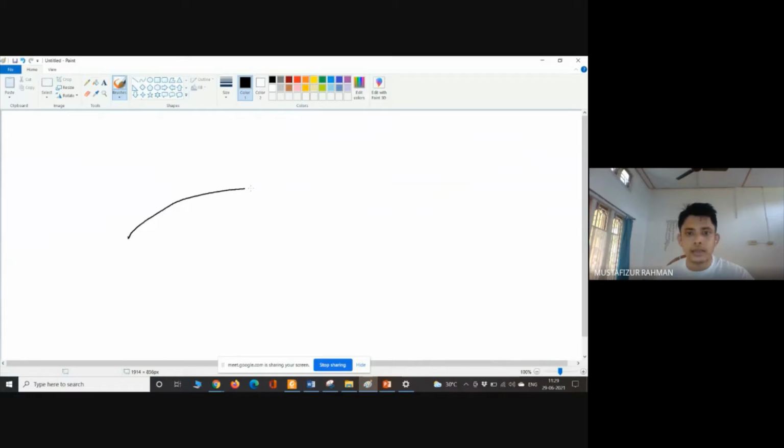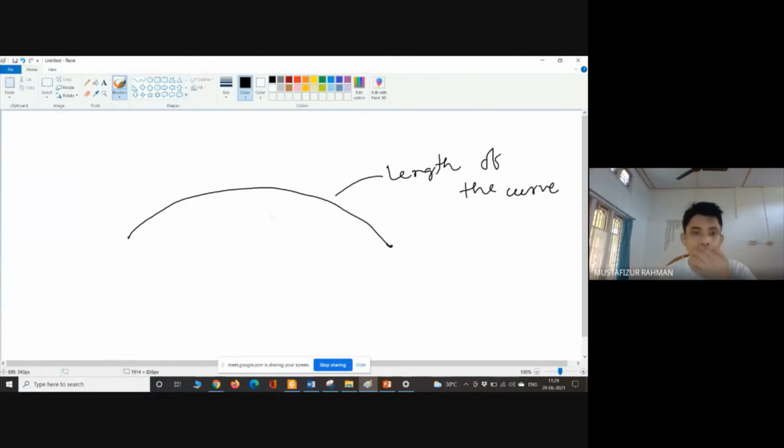So it was like this. This was the curve. We know the length of the curve, right? We have to divide it into suitable chords like this, a suitable number of chords. Most values are 20 meter. These are 20 meters, but the first and last are different, because we want to find these points at round numbers.